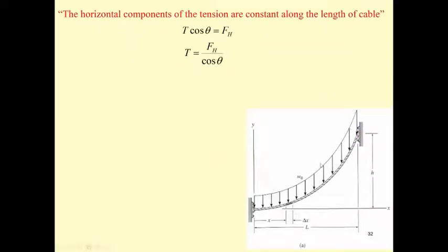And the horizontal force equation is a very important equation, because F sub H can be determined easily. And if you know F sub H, because it is a constant across the cable, you can find the tension of the cable at any point with respect to cos θ.